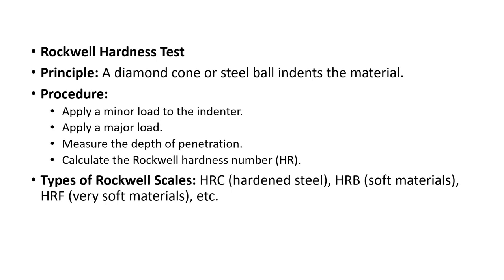Load calculations are fixed, and according to that, the load is applied to the diamond cone. Apply a major load. Actually we are applying a major load on the component, and as I already told, measure the depth of penetration. We have to measure the depth of penetration.